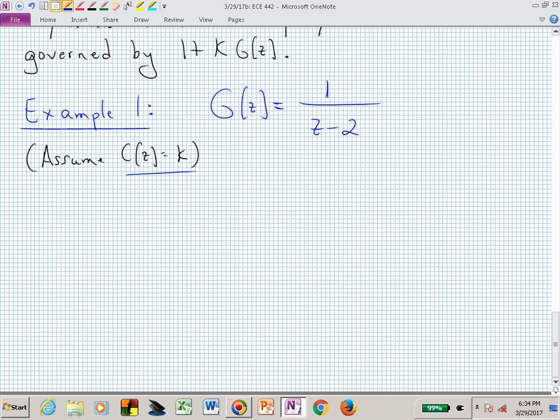You find the roots of your denominator, you find your poles, you look at their R's. In this case, where is your R? It's a 2, and you're now raising that to higher and higher powers of n. It's just going to expand, isn't it? So let's see what we can do with a constant output feedback.